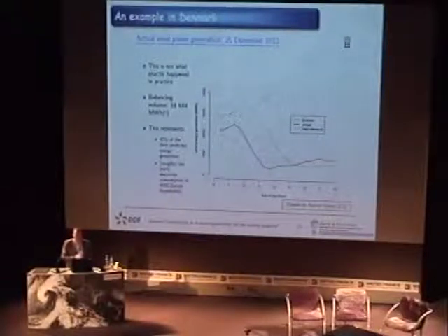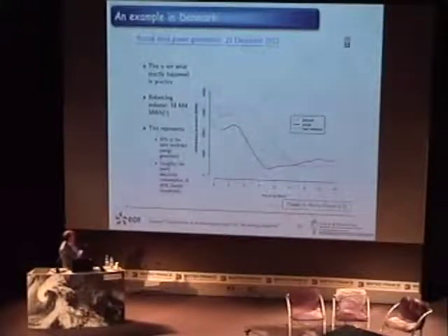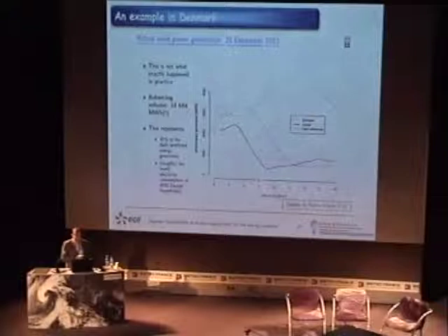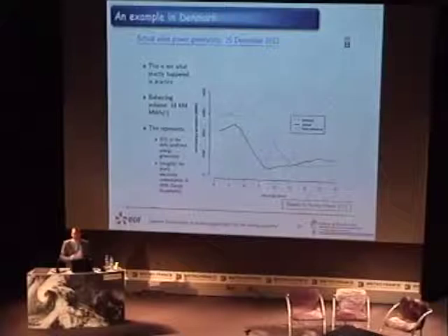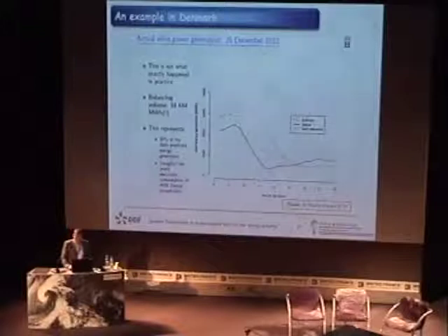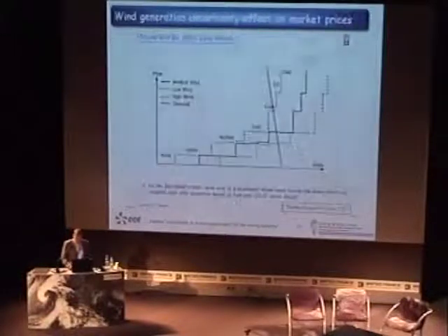And in fact, the wind was stronger in the morning, and the net load is the difference between the reference load and the production from wind energy. So the picture was this one, and when you calculate the difference between both, you have a balancing volume of more than 18,000 megawatt hours, which is something like 45% of the daily predicted energy generation. So it's quite huge, it's very important, and it's only a 24-hour forecast. So this poses problems to system operators.